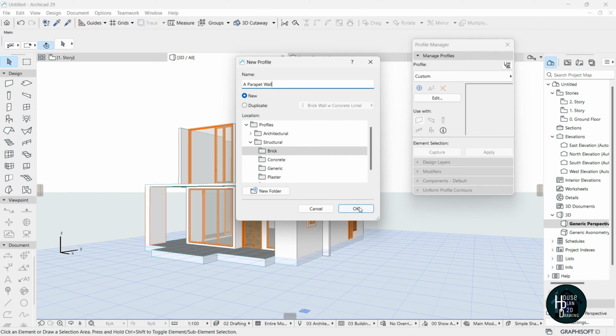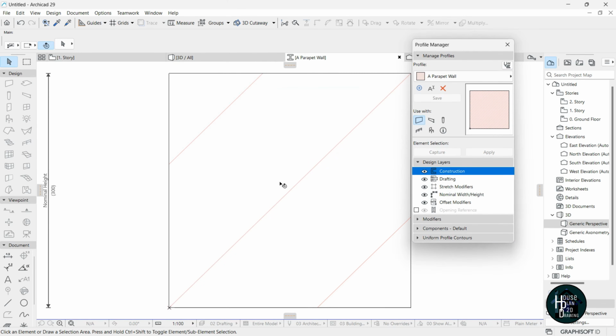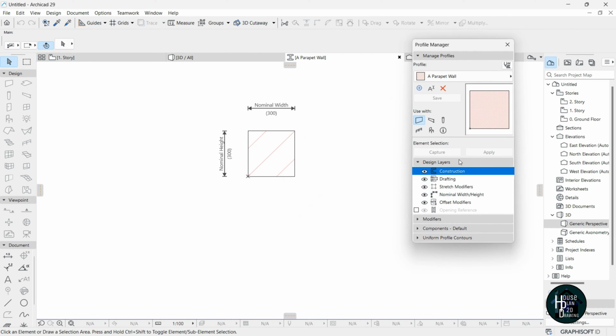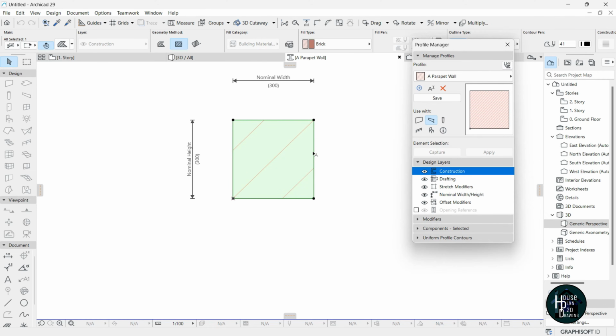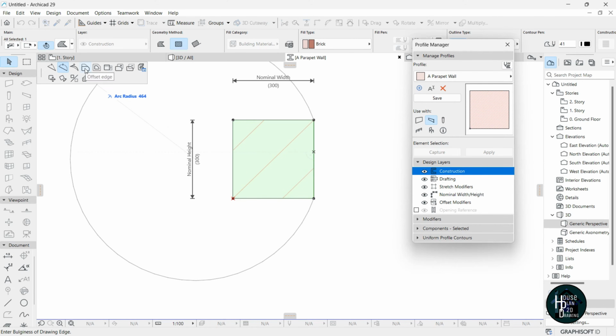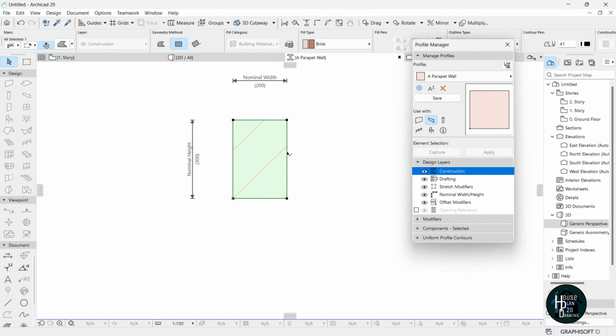So I was supposed to press new before. Once you finish doing this, just click on OK, and that's going to take you into this new page. You can just click this and untick this. It's very important you guys do that. Now click this, click on this edge, make sure you're selecting this offset edge and reduce this by 100. Click enter.